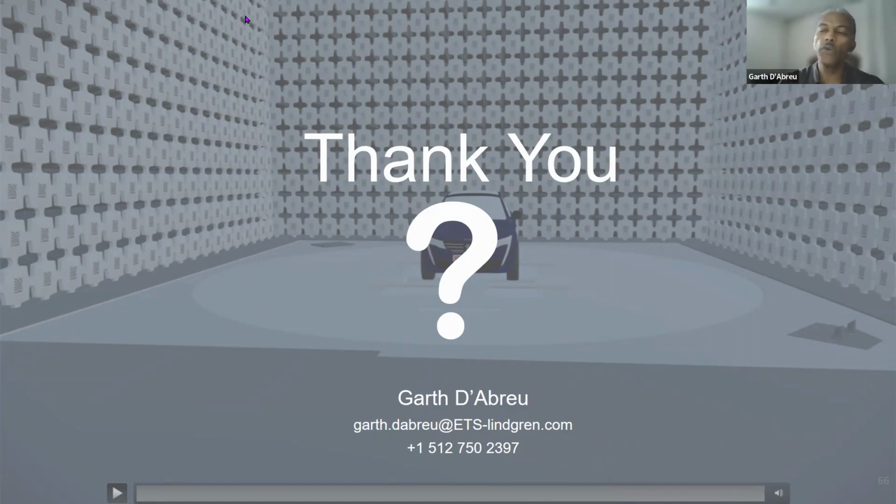On the other side of the coin, you tell the base station emulator to reduce its transmit power, and you transmit a known data packet to the device under test and ask, did you receive the packet error-free? Drop the transmit level. Did you receive the packet error-free? And you create a map of the received signal as a function of orientation, sort of an antenna pattern of sensitivity of the device. And it's exactly the same thing that's needed in the automotive industry, where you have these